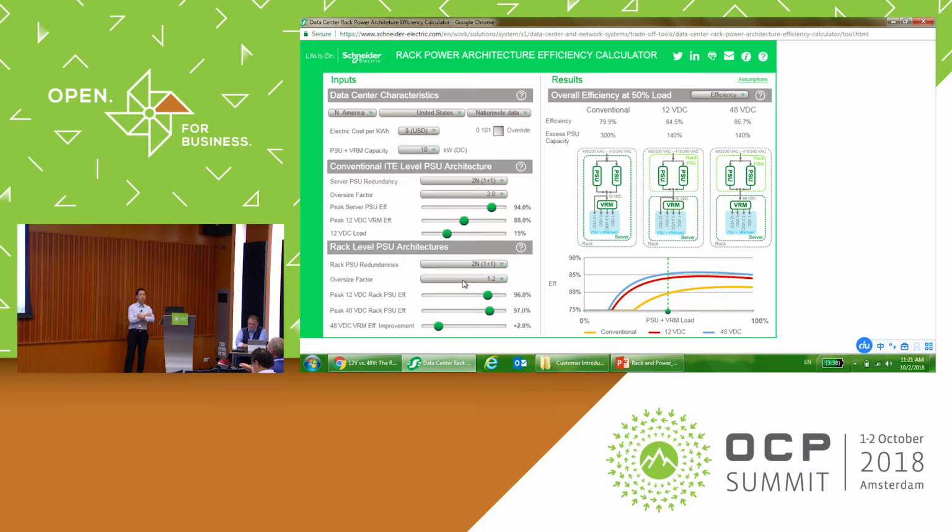So if the rack consumes 10 kilowatts for N plus N, in your model you would put in 24 kilowatts worth of power, 12 kilowatts on one feed, 12 kilowatts on the other feed? Yes, that's the N plus N configuration, and that's what this is modeling. So the 140% really would be 120% for each of the feeds?